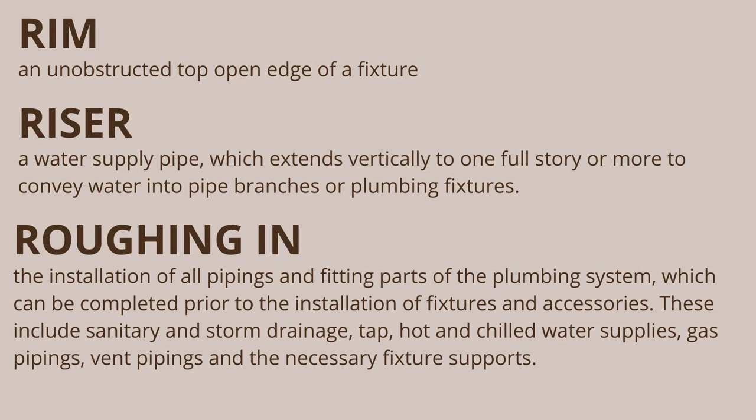Riser. A water supply pipe which extends vertically to one full story or more to convey water into pipe branches or plumbing fixtures. Roughing in. The installation of all pipings and fitting parts of the plumbing system which can be completed prior to the installation of fixtures and accessories.